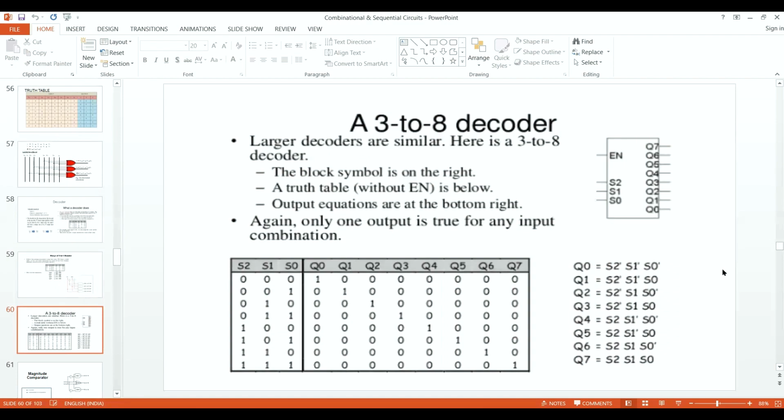Similarly, for a 3 to 8 decoder, the inputs are 3 different select lines. We are going to write 0 to 7. And similarly, when the input is all 0, Q0 would be on. Then when 1 is there, Q1 is on. When the 2 is there, Q2 would be on. And all the diagonal elements would be shown over here. I am telling you the trick, beta.